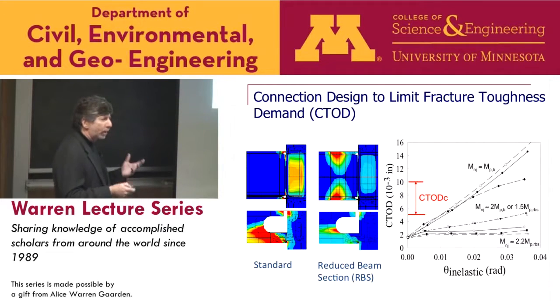So we did this work at the time and we're able to, for example, apply these sort of models to look at different design parameters. I won't go through the details here. These were some beam column joints, looking at the relative strength of the panel zone to the reduced beam section to force yielding away from this welded region.